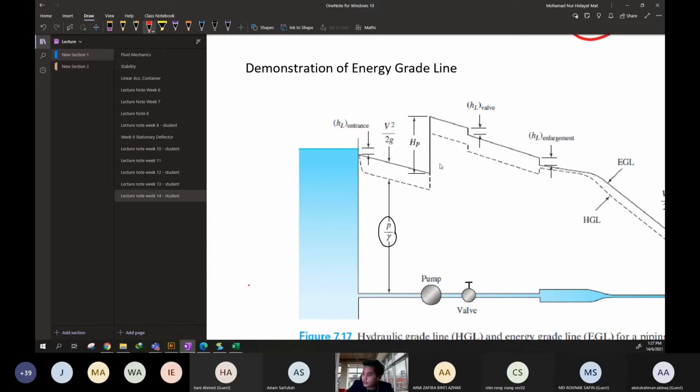All right. And then we have the pump. The pump will increase the pressure as well as the velocity. Due to the pressure increase, the velocity increases. So the velocity increases and decreases due to the major losses, and we have the valve to regulate the fluid, which drops slightly. You can see the difference here is the HL, head loss, from the valve only.